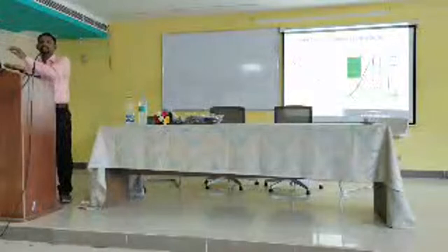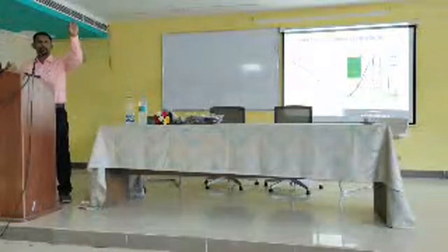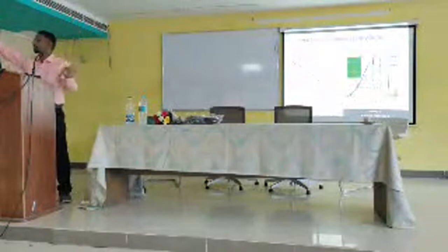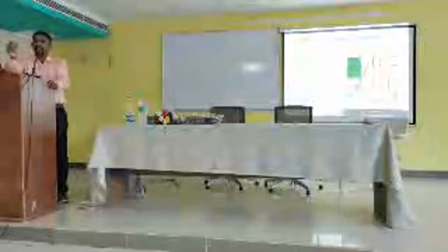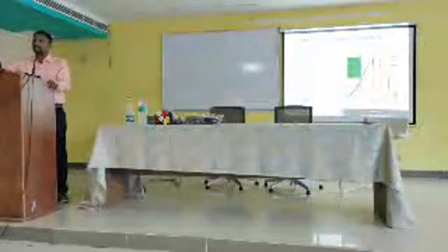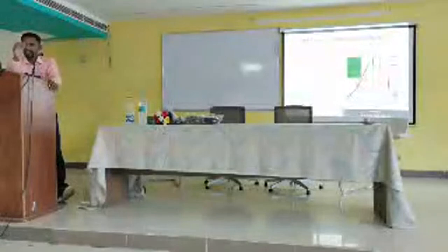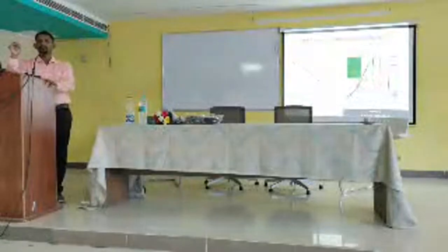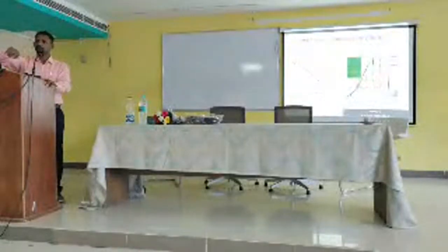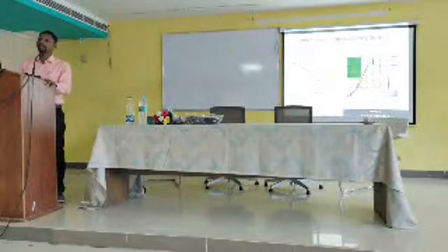By having a lookup table of the intensity with respect to the salinity level, the display will tell you that your water has 100% salinity. In this way, the photonic sensor is going to work. Here I have shown only the intensity reduction scheme. And there is another possibility, the wavelength shift scheme.